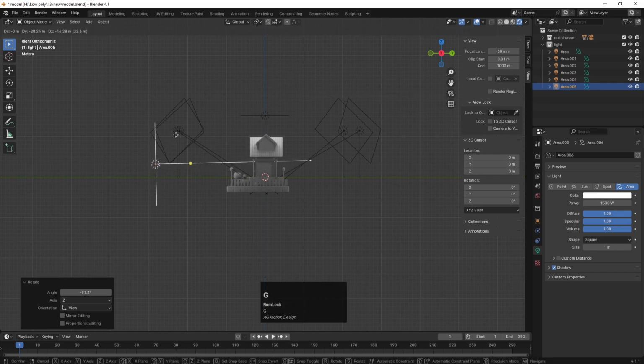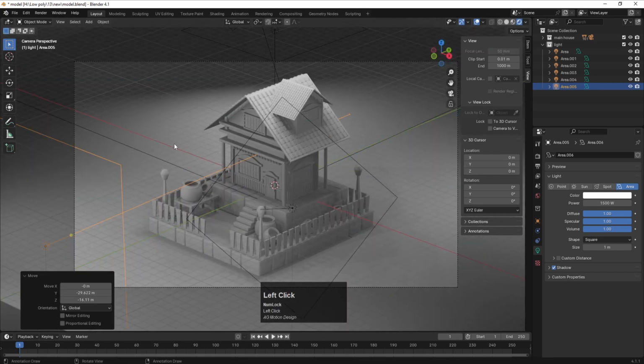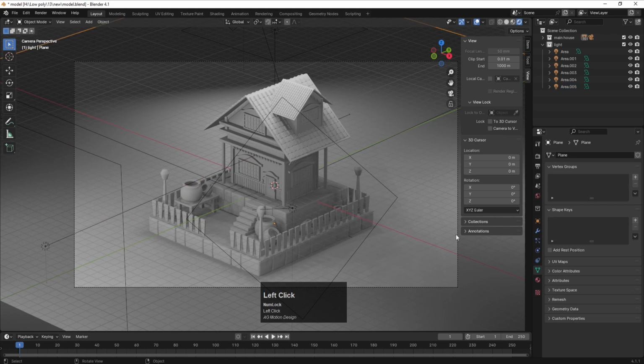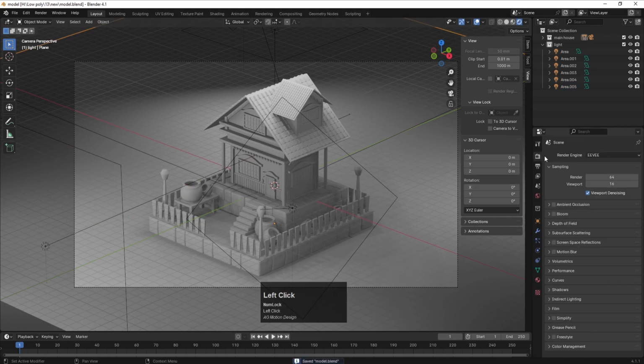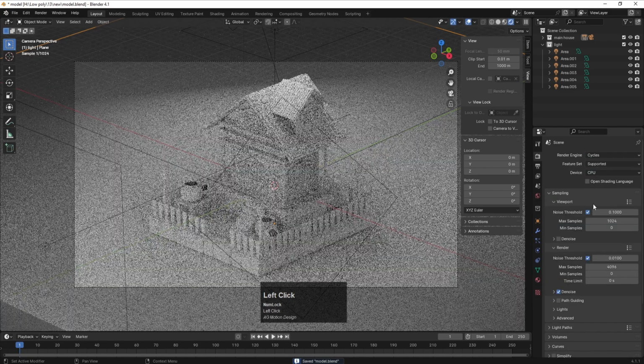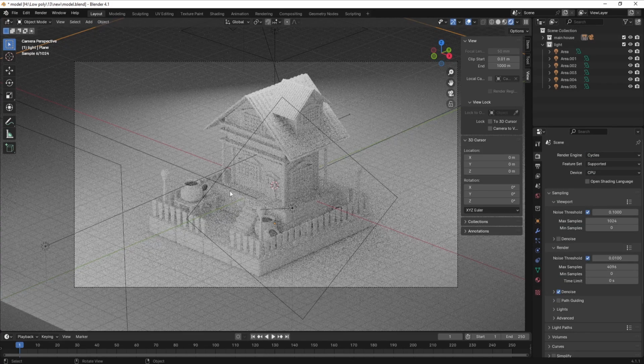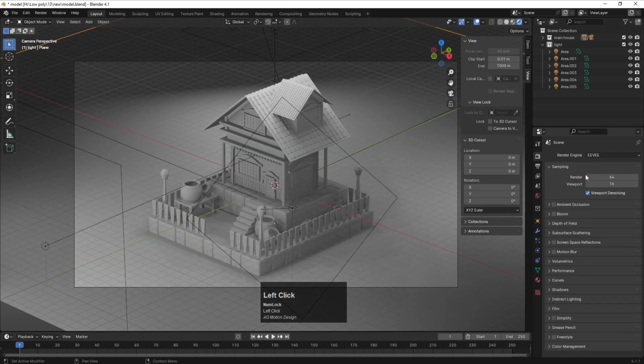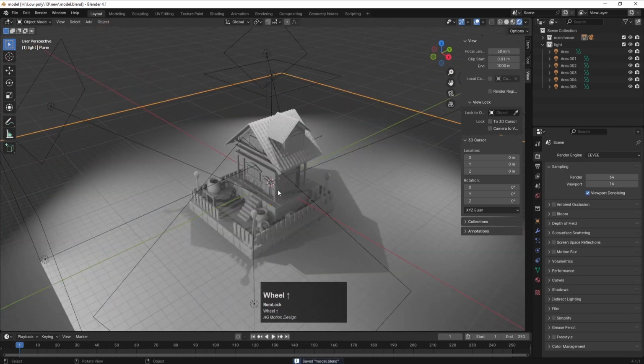And let's try to bring this over here and hit 0 like this, and let's increase the power to 2000 like this. Okay, so we'll get this portion. Let's select this, and now we will apply colors to it. But before that, let's see how it looks in Cycles. As you can see, it looks something like this. So let's go to the EEVEE rendering system, and hit 0 to get out of this camera view.